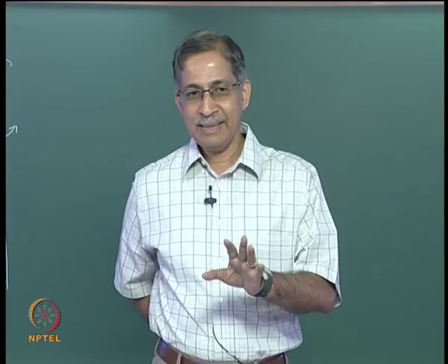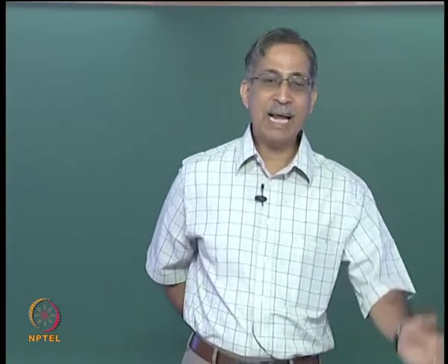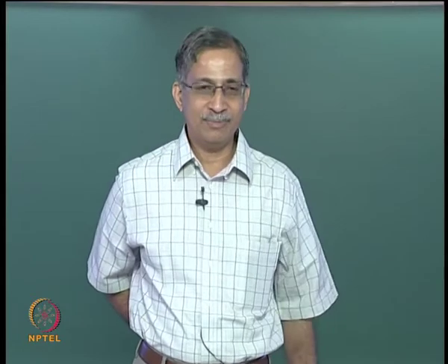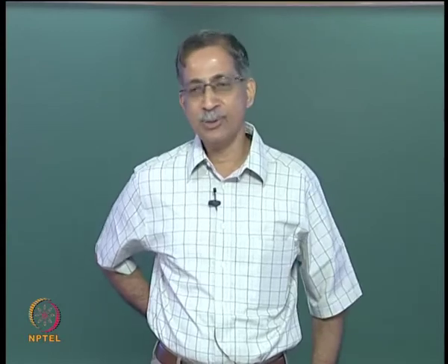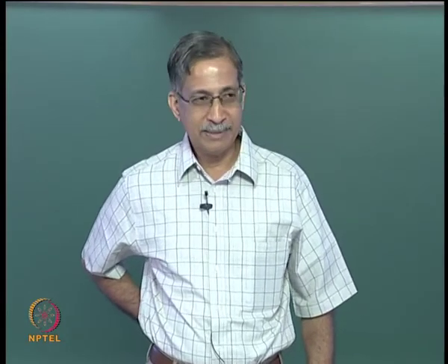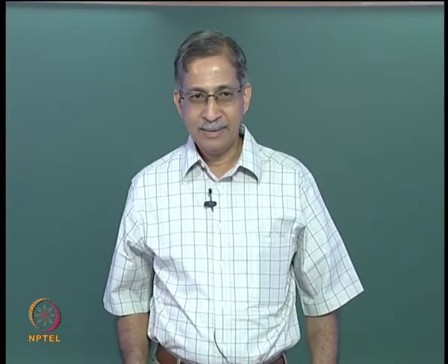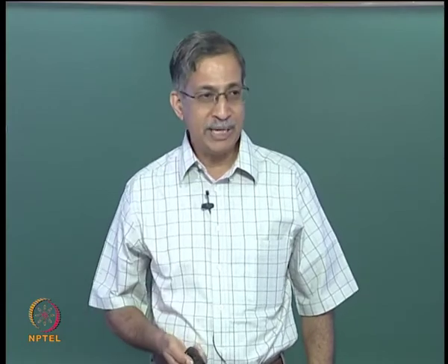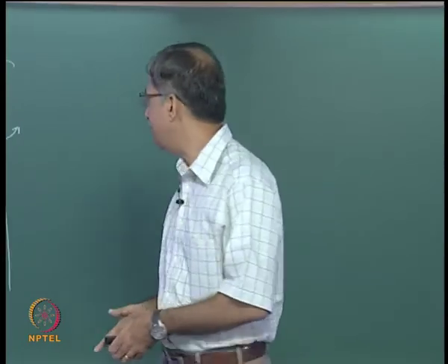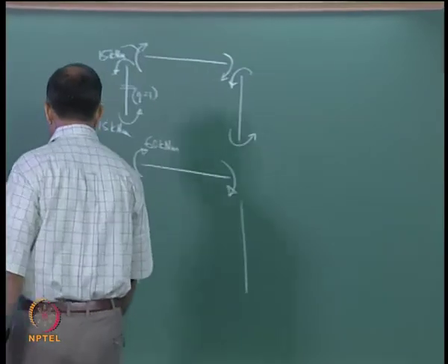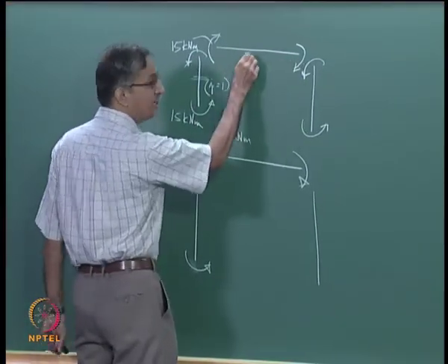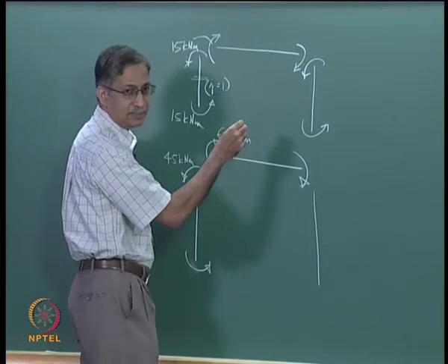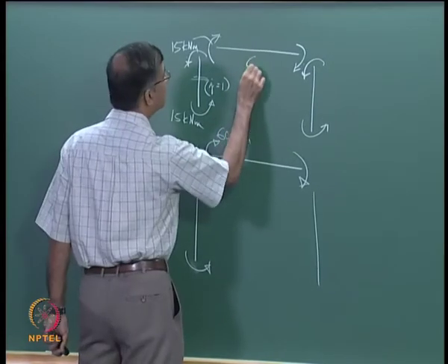Now, let us ask a question, how do you calculate the drift in this frame? Because people would like to know how much the building will move on the top. You can also get the interstory drift. How do you do that? So that, okay, you can also get the beam shear. How do you get the beam shear? Well, if this is 15 and this is 15 and the span is how much? 6 meters.